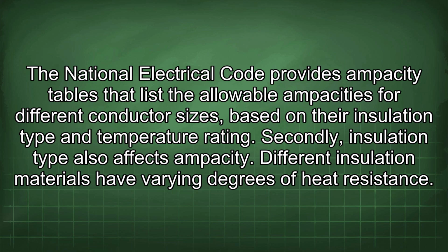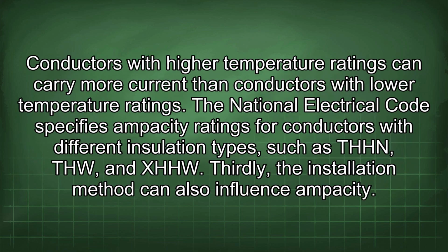Different insulation materials have varying degrees of heat resistance. Conductors with high temperature ratings can carry more current than conductors with lower temperature ratings. The National Electrical Code specifies ampacity ratings for conductors with different insulation types, such as THHN, THW, and XHHW.